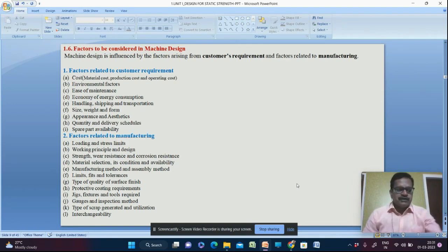Interference fit is useful in shrink fitting of an object, where one object needs to be placed in another object. It will be heated, and when heated it can enter easily, but after cooling down the two will act together as a single component, and that process is known as shrink fitting. So in the shrink fitting category we are going to have interference fit. So right now you have interference fit, clearance fit and transition fit.